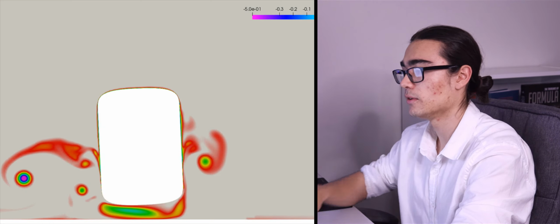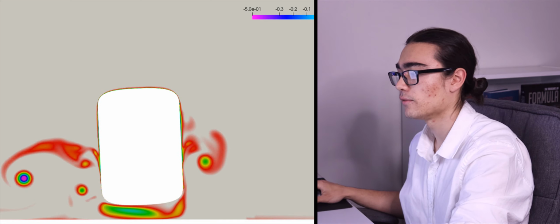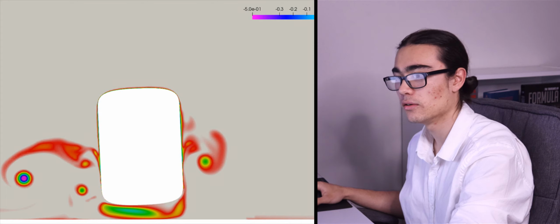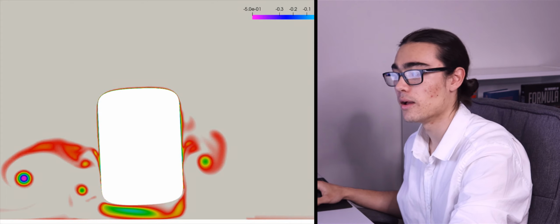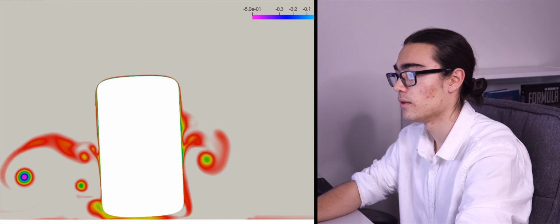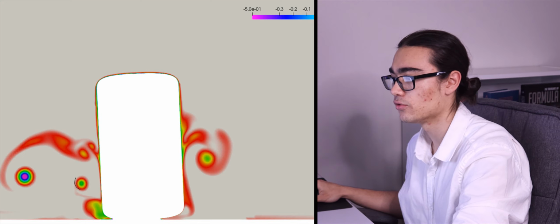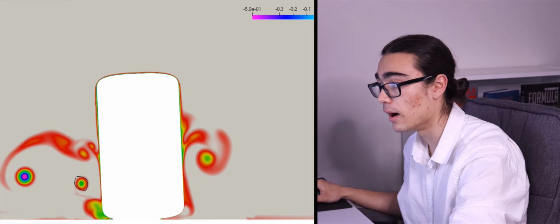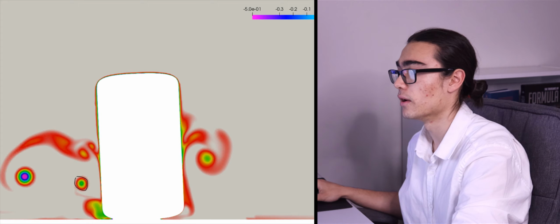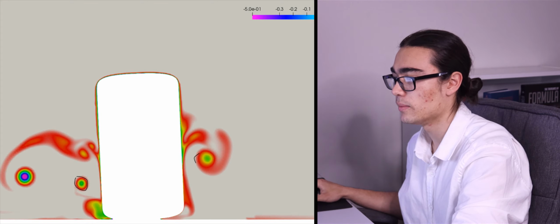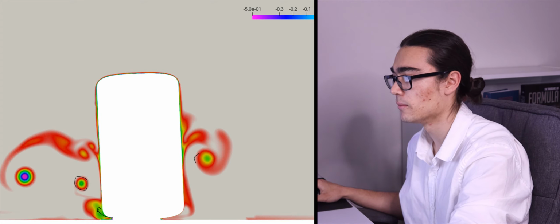Now, similar to before, we've got our mass flow here. It's working to push some of the loss out of the way, not necessarily a good thing, because it's going to squirt our loss out of the sides. Okay, so we've got some very defined structures here. That's our bottom strake, which has been kicked up quite high, and we've got our canards still, and now we're beginning to get some squirt out the side.